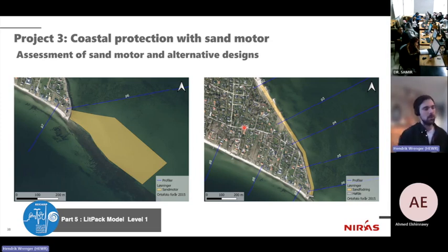We will, as I said before, collect bathymetry data. We probably collect some more extensive sediment information. And as we zoom into the details, we might in the next iteration use other models. We might set up a coastline evolution model, or maybe even some 2D modeling around this headland, so outside the LitPack suite, which then will only be for individual events, right? We can't model the whole thing in 2D for 10 years.